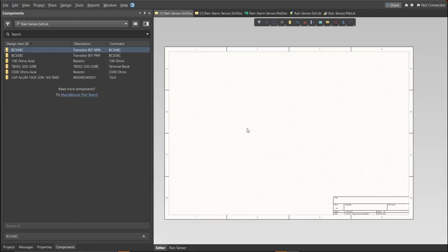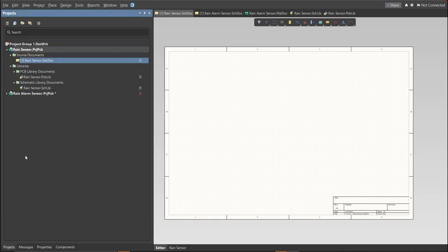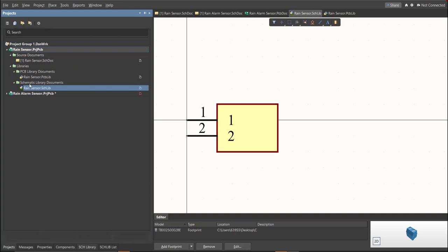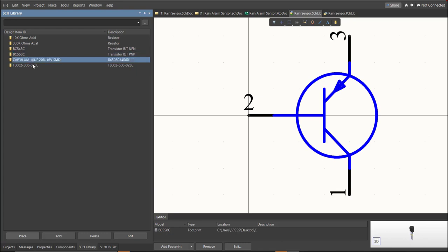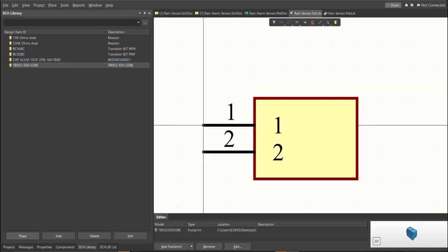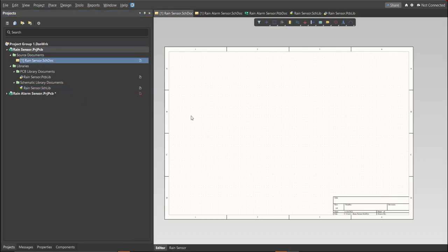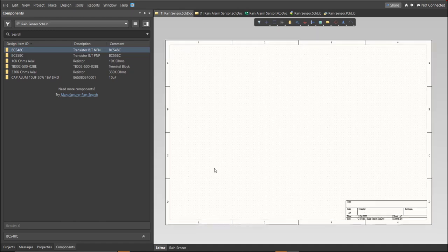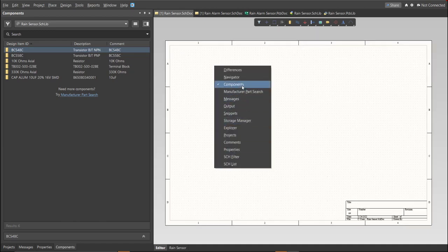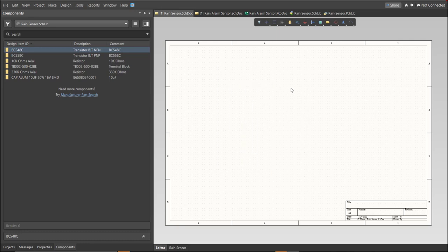After you finish all the components in the BOM list using the library loader, you can check in the schematic library panel all the added libraries. These are the added libraries for this PCB. Next, we're going to put all of these in our schematic doc. So go back to the schematic doc and click on Components. If there is no component in your panel, just press K on your keyboard, then click on Components. Now you can see here the library for this project. We're just gonna drag the library inside the schematic sheet.